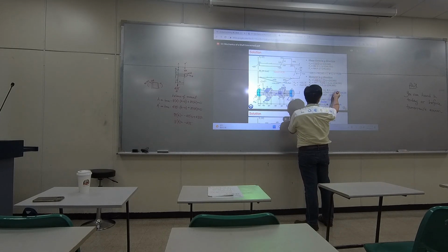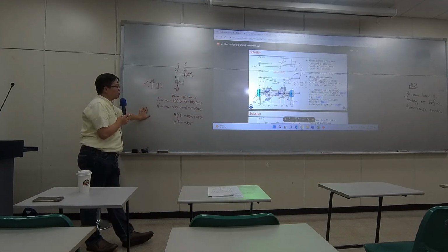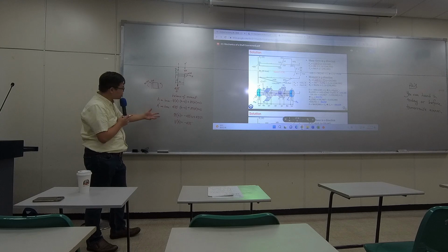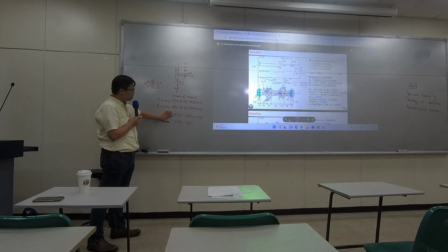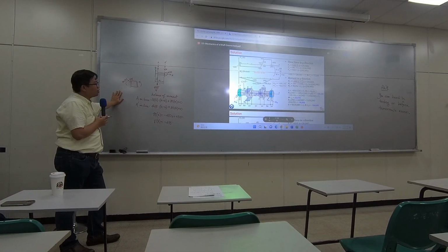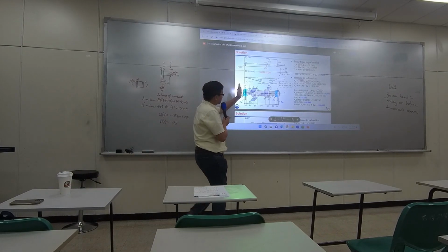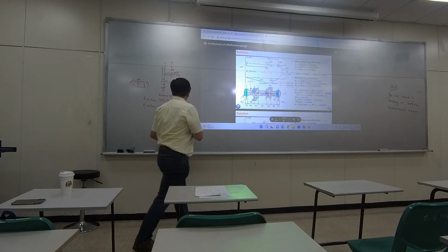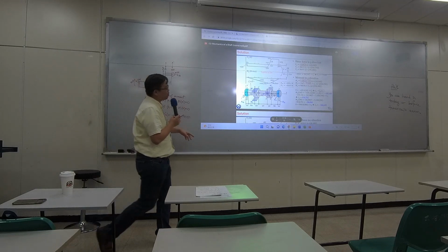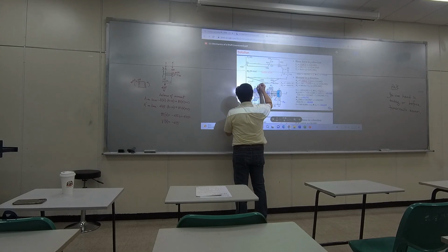My C2 was here. So you can tell this is a different way to directly compute the shear force and the bending moment. By this way, you don't really need to take integrals. Okay, so you just need to keep on making cuts and then formulate balance of moments, and you should be able to get all the equations. And they are supposed to be the same equations. So let's try to make a cut right here. So another cut.